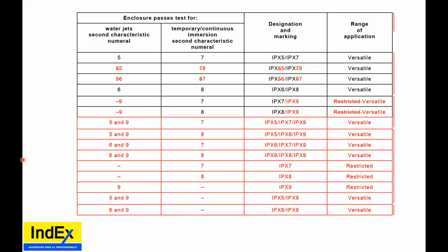The exact phrase in the standard is that 7 and 8 do not cover 5 and 6, but no mention of 4 and below. The reason it doesn't mention that is because when you go within the standards and cover IP66, it does tell you that 6 covers from 1 to 6, 5 covers from 1 to 5, 4 covers from 1 to 4. So they didn't go into too much detail. This is already confusing for people. They didn't want to make it more confusing.